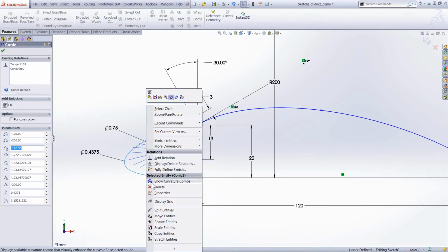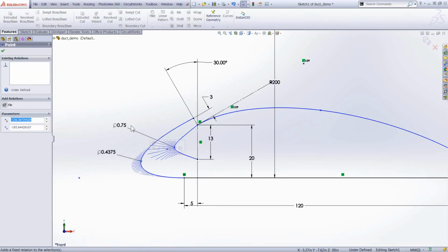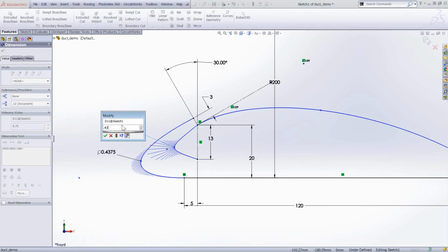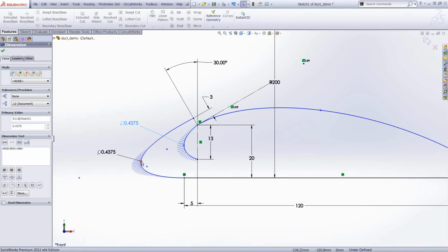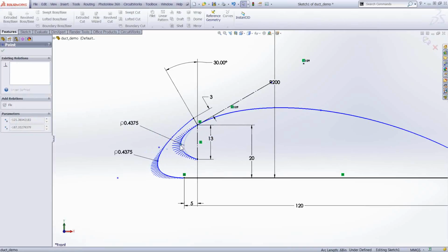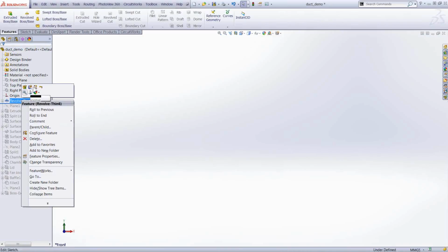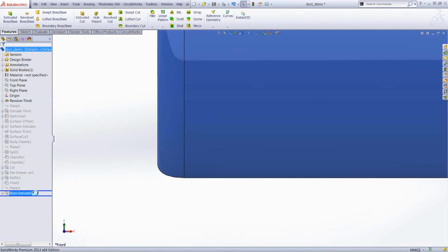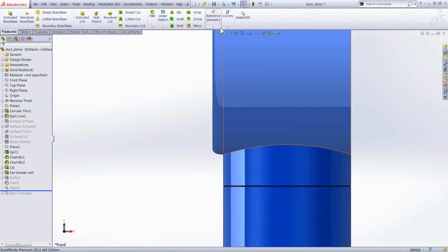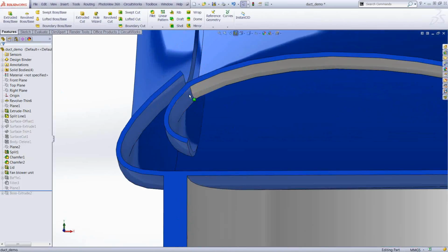And by showing the curvature cones on this conic, you can very easily use it to create and match up other curves that are in your sketches. So if I set this the same here, it makes it quite easy to match up these curvatures. I can also dimension to these points, create relationships like tangency and so forth. So once that conic is completed in that part, hopefully you can see a very nice reproduction of the original curve there.